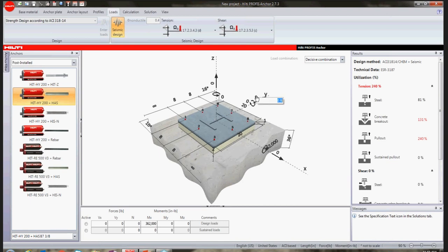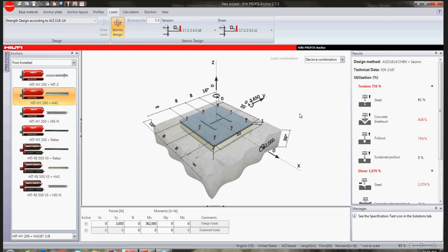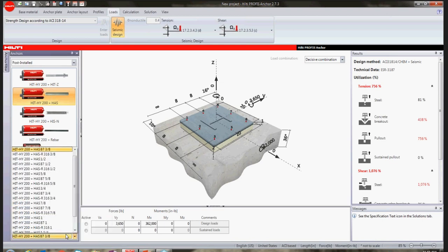Our application is going to be standoff with grouting. Because if you take one off, you don't get it. But we essentially give you 4 options, and the reason why we give you this is because Hilti is taking into consideration the flexural bending of the fixture when standoff is used.